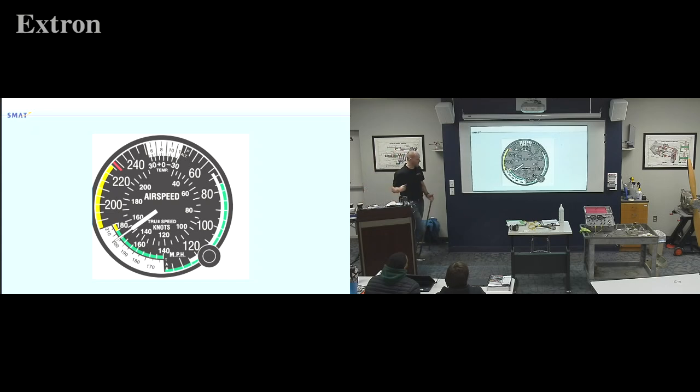Yep, we'll explain it one more time. So this white section here, as I turn this dial, is going to move. All these numbers are going to move, because they're going to get adjusted for my outside temperature. So we're assuming, because I told you we're assuming, we're at 10,000 feet.